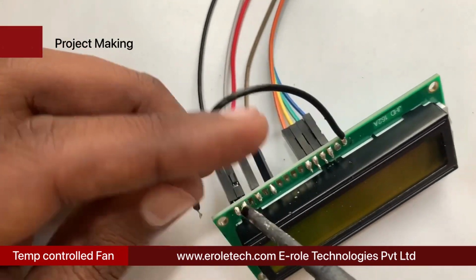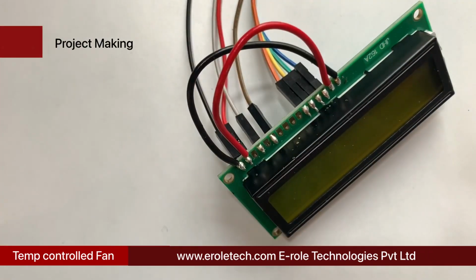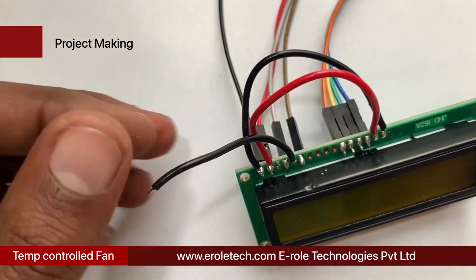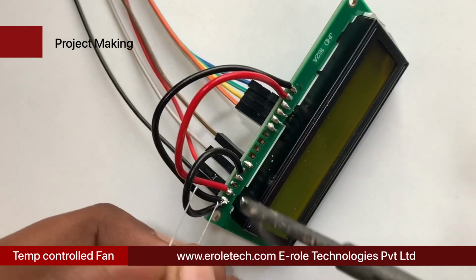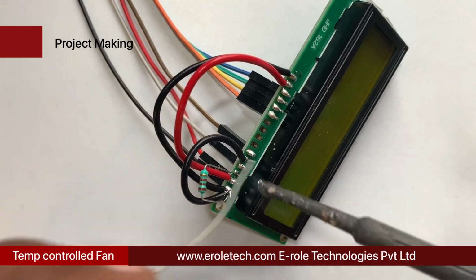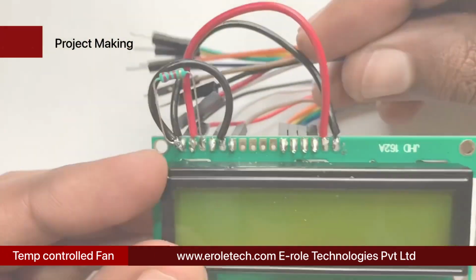Now connect hole number 16 with hole number 1 using a black wire, and hole number 15 with hole number 2 of the LCD display using a red wire. Now connect hole number 5 with hole number 1 of the LCD display using a black wire. Now connect hole number 3 with hole number 1 of the LCD display through a 1 kilo ohm resistor.